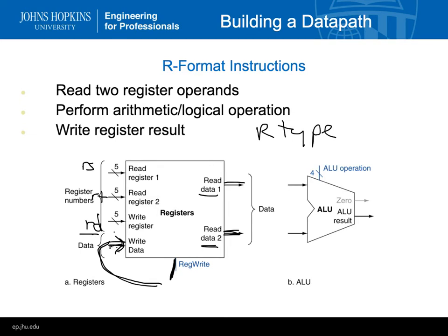And then this is the ALU, which we'll talk about. We're going to give it 2 values and get a result. And there's several operations that we can do: addition, subtraction, AND, and OR. And again, we're going to have these control values come in. There's a 4-bit control value that's going to come in and tell the ALU which of these operations you want me to do.